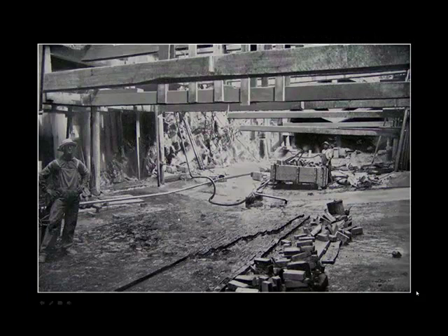Here, some membrane of waterproofing has been applied to the floor, and it is being protected by layers of brick. The brick here is set in mastic, which is a kind of an asphalt material. So you have a mud slab, some kind of a membrane, and then multiple layers of brick and mastic, which protects the membrane and at the same time provides a waterproofing in itself. And a similar treatment will be carried up the side walls.